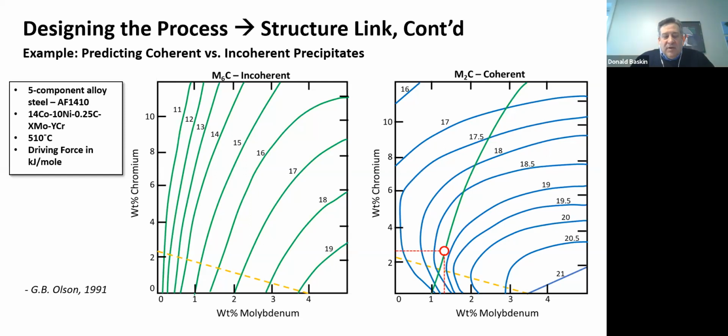This alloy is a precipitation hardening steel. So not only can it be martensitic, but it can also have precipitates in it that stop those dislocations from moving, make it require more energy in order for the dislocations to move, which increases the strength of the material in the far field, where you're going to use it as a structural engineer designing a bicycle frame or a bridge or an airplane fuselage.